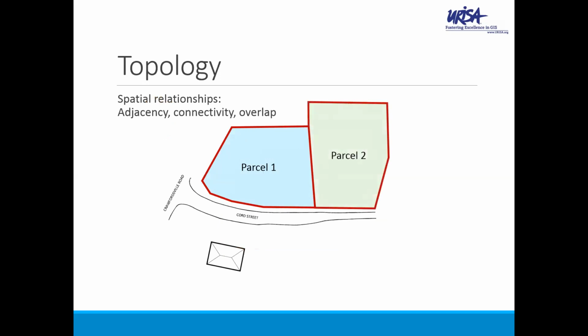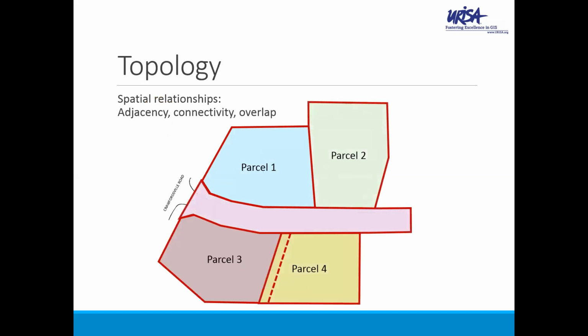Now we can just touch on topology, right? Topology represents the spatial relationships, and these are ubiquitous in GIS, whether in the mapping of parcels or soil types or impervious surfaces, or a multitude of other potential features. There's an expectation that for each type of feature, each discrete area will be independent of its neighbor with no overlaps or gaps. Otherwise, any analysis becomes suspect.